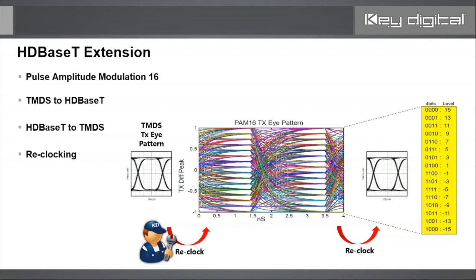And if that severe electrical noise were to occur, and if it cuts through that 1 and 0, corrupts that data, you've got nothing. Well, pulse amplitude modulation, PAM16, enables it so that if that severe noise occurs, it likely will affect only a range of frequencies within that cable, not every frequency. So that's what makes it ultimately reliable, is having 16 different instances of the data to work with.